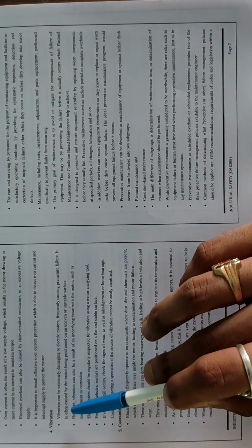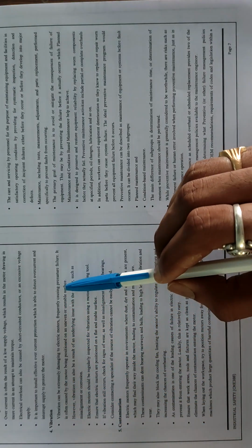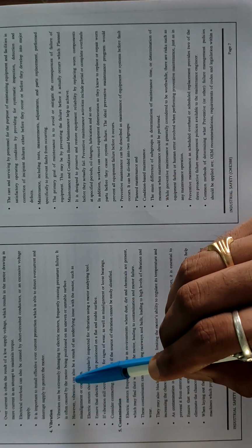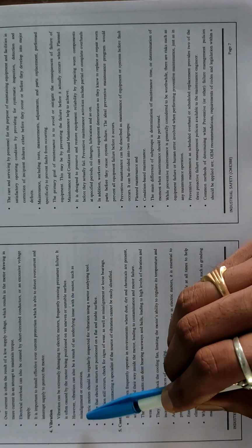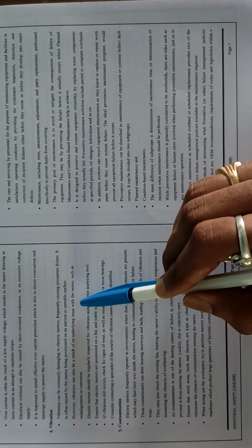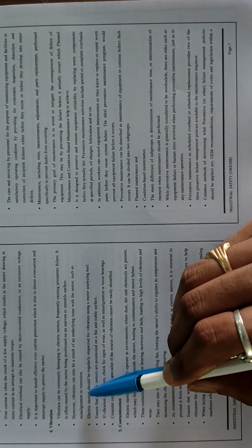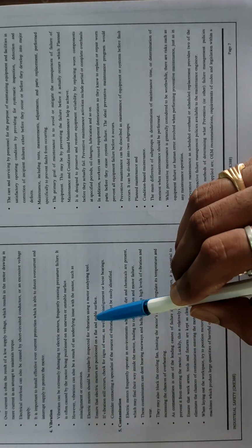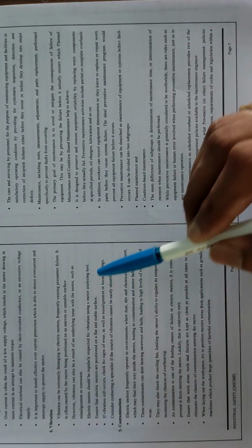Vibration. Vibration can be extremely damaging to electric motors, frequently causing premature failure. It is often caused by the motor being positioned on an uneven or unstable surface. However, vibration can also be a result of an underlying issue with the motor, such as misalignment or corrosion. Electric motors should be regularly inspected for vibration using a motor analyzing tool.